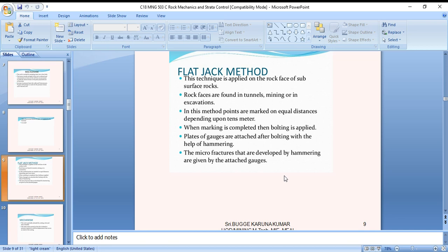The process of cutting the structure free from its surroundings is referred to as strain relief. If the elastic properties of the pillar rock are known, the absolute stress can be calculated, and the process is referred to as stress relief. In fact, the terms strain relief and stress relief are used almost synonymously.